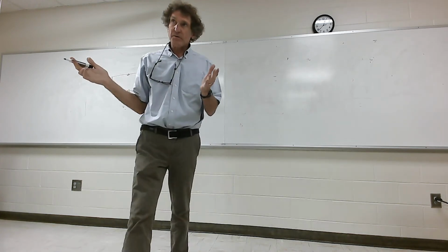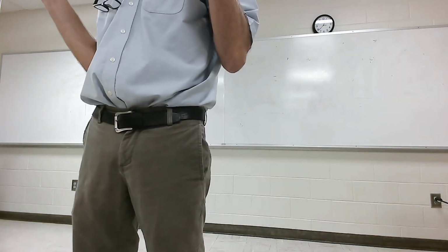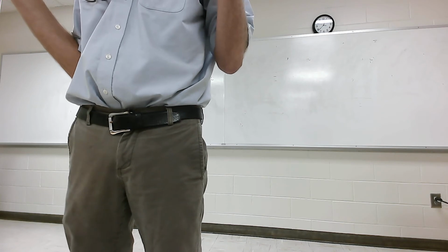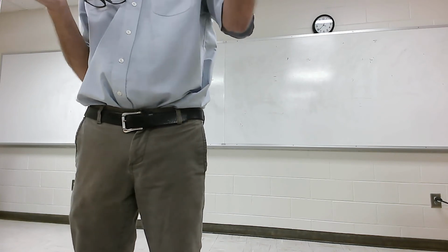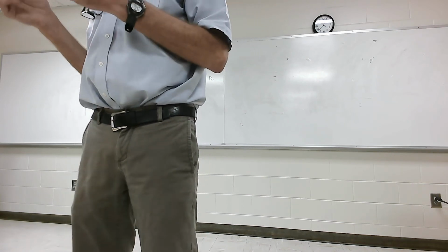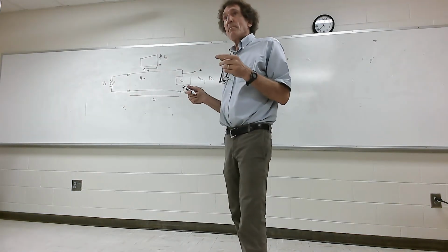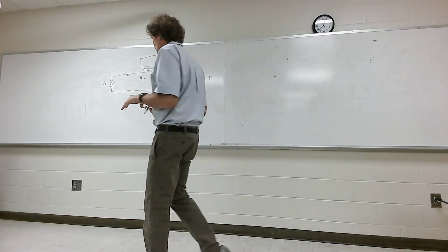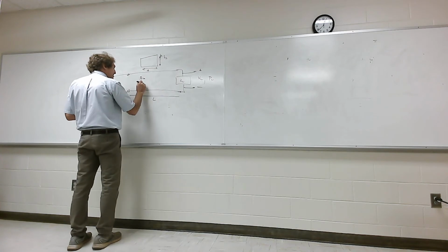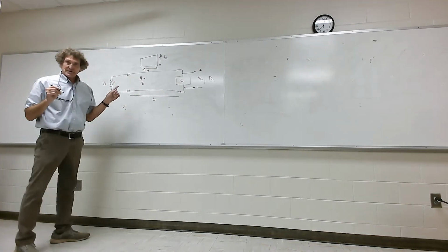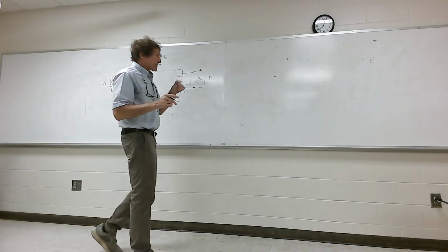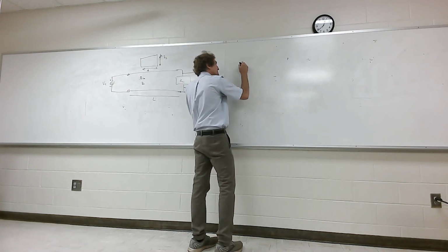Alright? So how do you remember this one? I gave you a problem on this. I gave you a couple problems on this. I gave you a quiz on this. Okay. So how do you do that? Well, probably the key thing to remember is you're going to have to get the characteristic impedance of that guide, right? And that means you have to figure out first the cutoff frequencies.